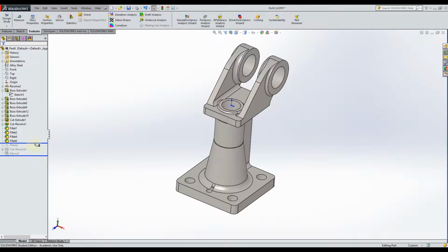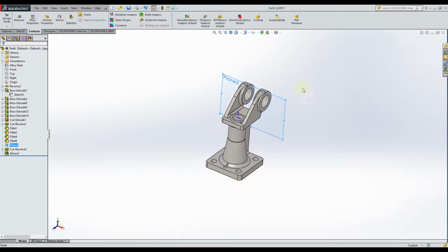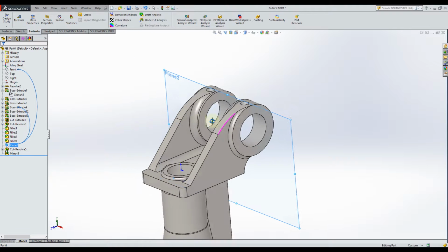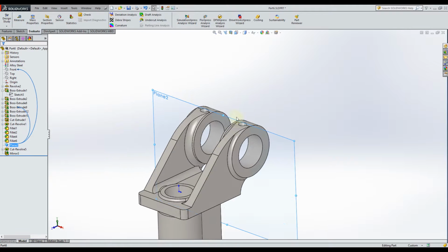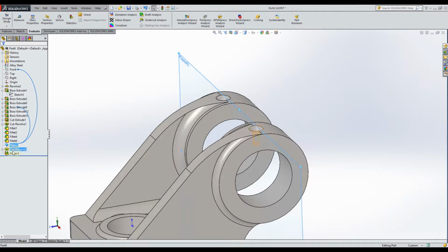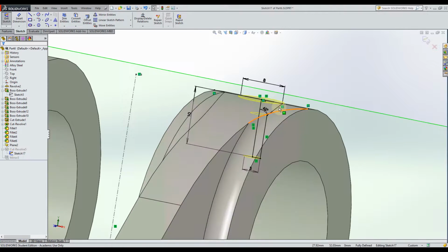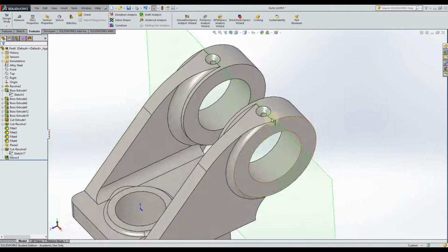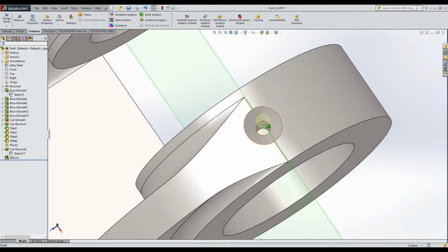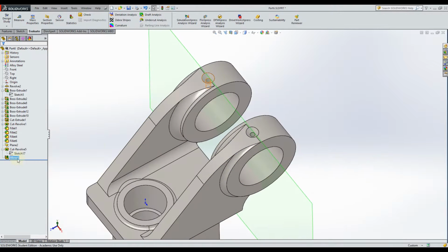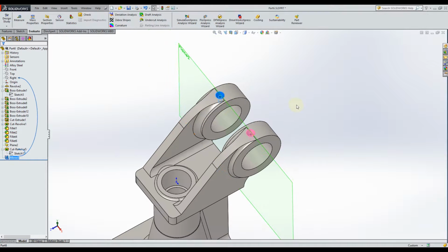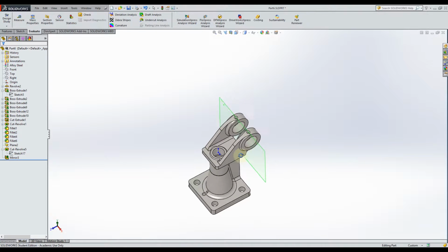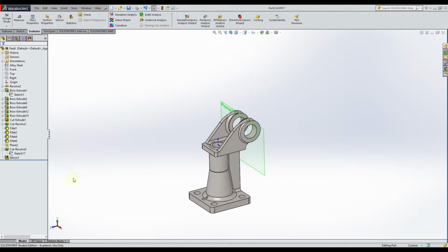If you look at my left, you can see I'm going to do rollback here to a previous version. Here I've added a plane, and I've added the plane to actually create this revolve. I'll show you the sketch. So this sketch revolves around this line, creating this chamfered cut extrude, which is then mirrored to the other side. So we've also used the mirror feature here.